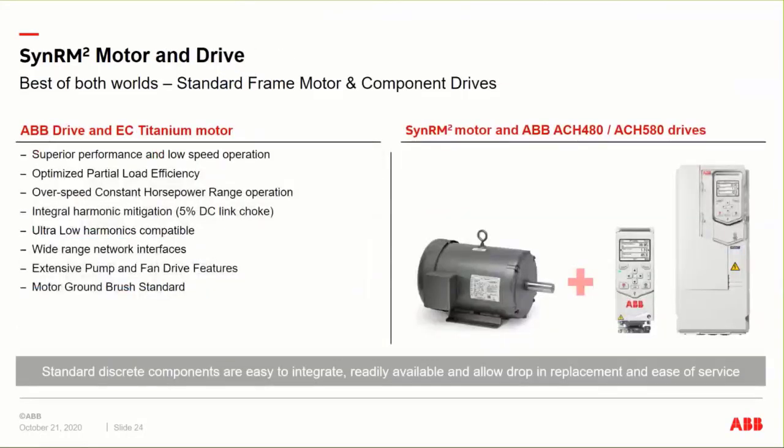Again, I'll reiterate on this. It uses standard components. So if you're replacing an induction motor, this is a drop-in replacement for that. It uses well-known power converters like the ABB ACH580, which has firmware directly to support this motor design. So they're standard discrete components. They're easy to integrate and they're readily available. So these are all stock components that we just put together and provide as a system.